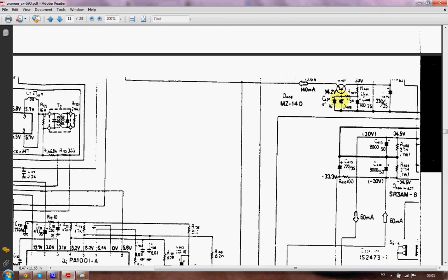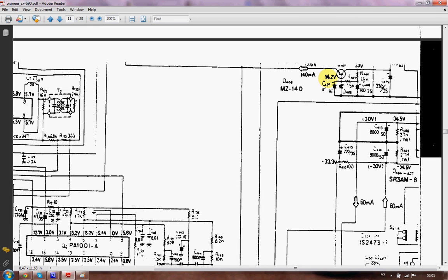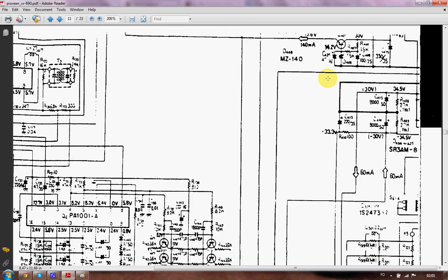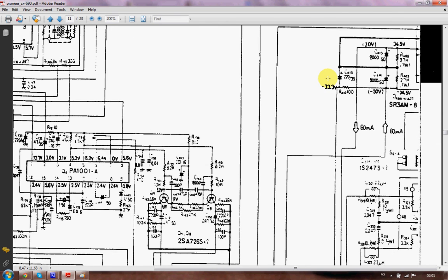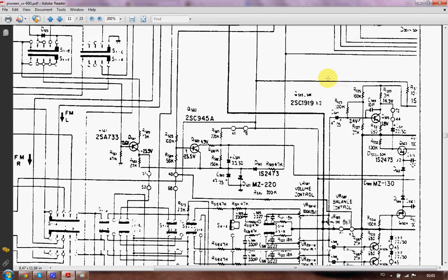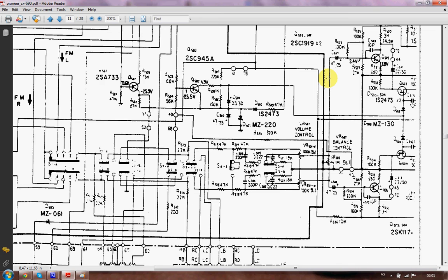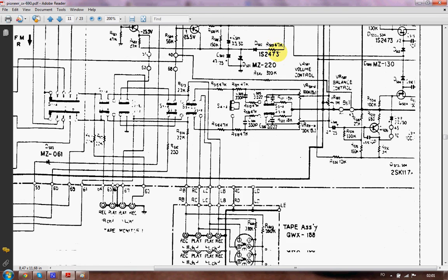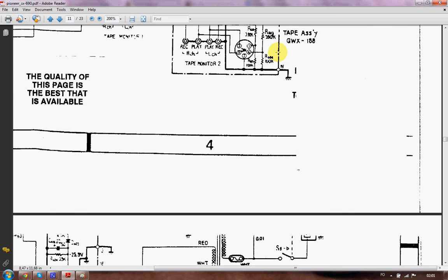And sure enough, I desoldered the transistor and tested it with a diode test. If you want to know how that's performed, just look up how to test a transistor with a multimeter. It's very easily done, but it requires removing the transistor, of course, so it won't be misleading by going through other components. So given voltages are fantastic when you're trying to localize a fault. They're the best aid you can get from a schematic diagram, in my opinion.